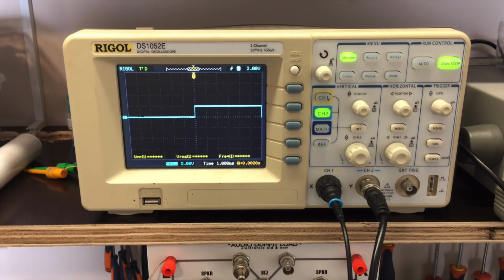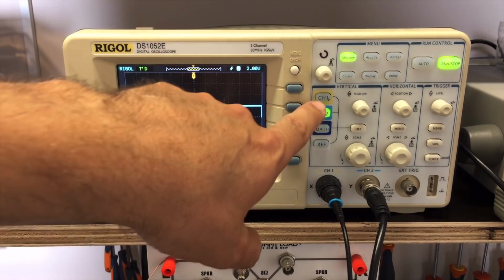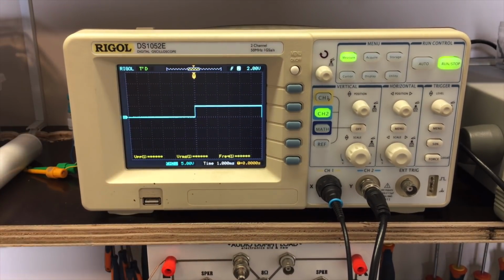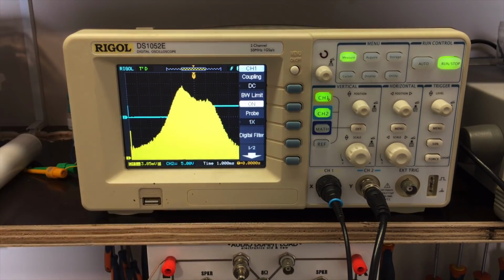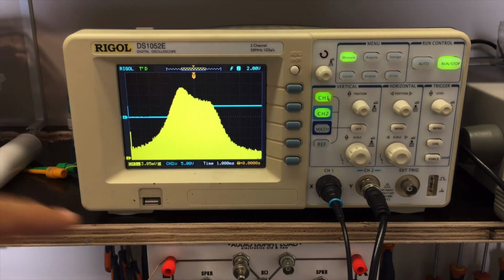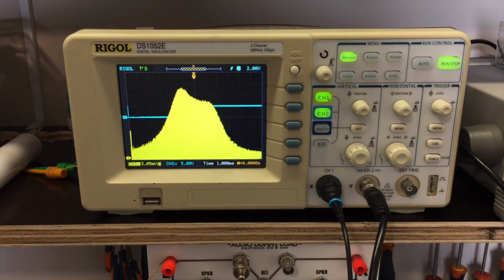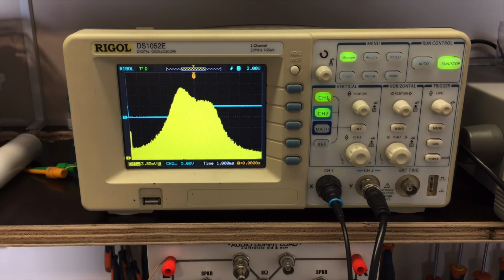And what I want to do now is see what result I get from that, basically that set of filters. Okay? And because I've got channel 1 connected to the output of that RF detector, which is connected in turn to the collector of that transistor as they indicate, this is what we get. I've got the scope triggering on channel 2, obviously. This is what we get.